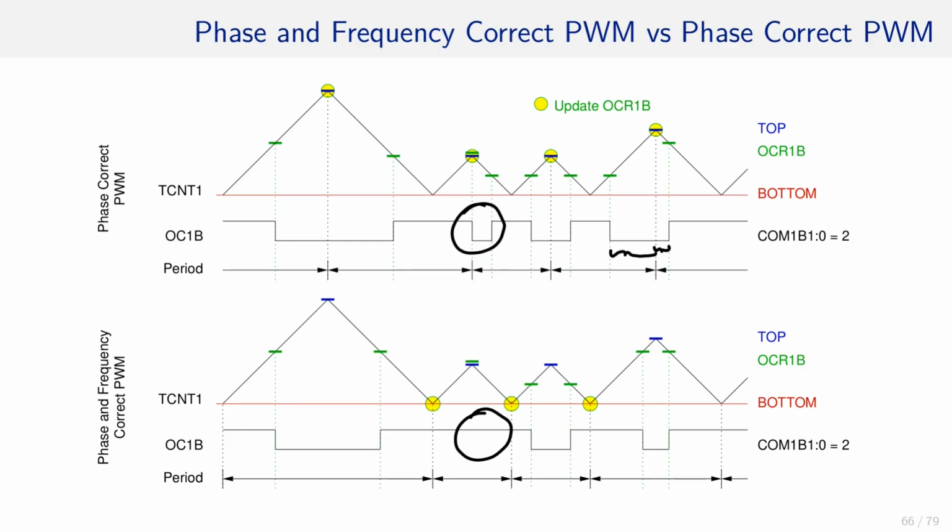If that symmetry cannot be established, the toggle is skipped entirely and postponed till the next period. It prevents spikes or glitches from being created even accidentally. And we already said that glitches are bad, especially for motors, a scenario phase correct PWM modes are destined for.